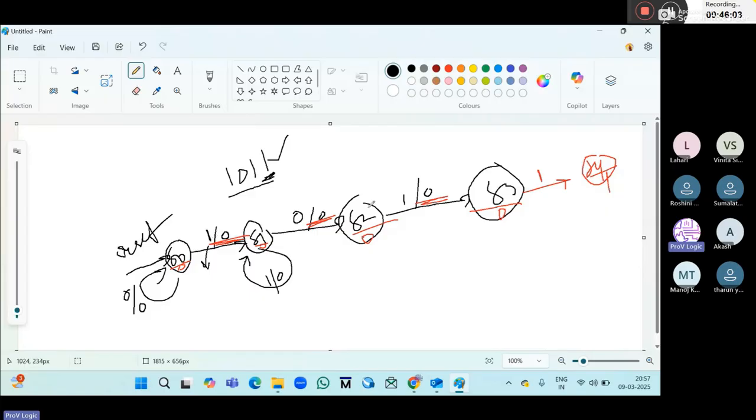Okay. And coming to S2. S2 is passing 1 here according to the sequence. Then what about 0? It can go to 0 here. Suppose the input is 0, 1, 0, 1, 0, 0, it can still detect the sequences. Anyway, it's a reset state, right? Reset means it will start from this 1 onwards. Even if it goes to 0 here, that's not a problem. 0 by output is also 0. Okay, next coming to S3.